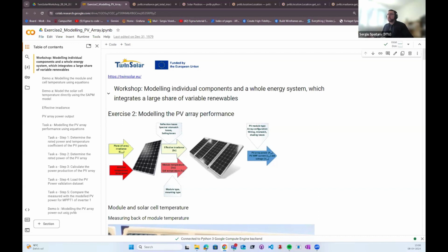Another thing we'll talk about is the spectral sensitivity of the solar cells. Some solar cells do not absorb the entire energy spectrum of the incoming light. So even though some light reaches the top surface of the panels, they are only sensitive to and absorb certain wavelengths.